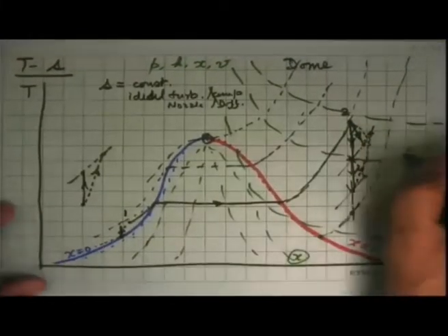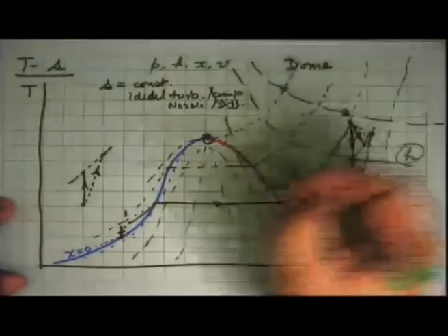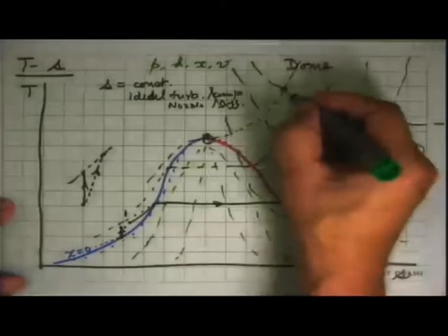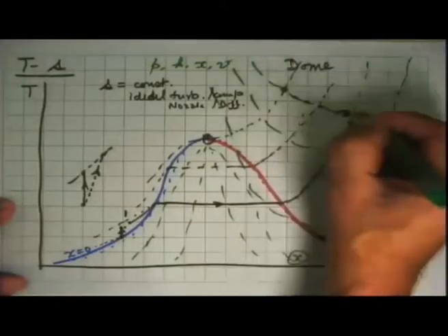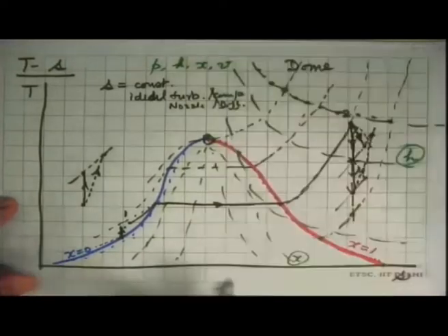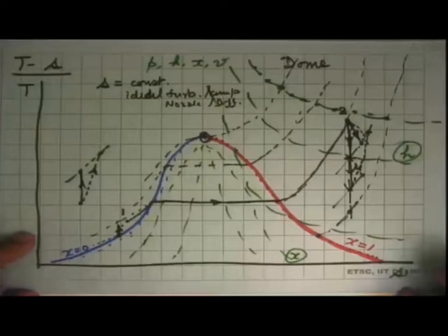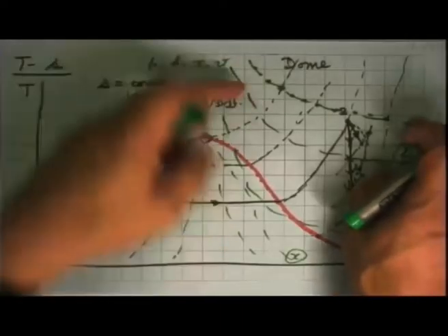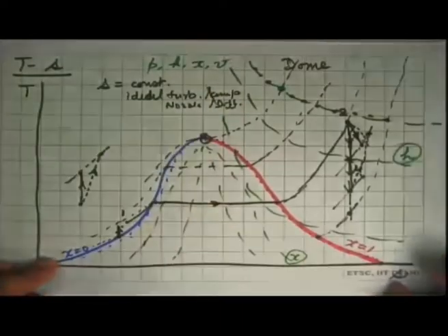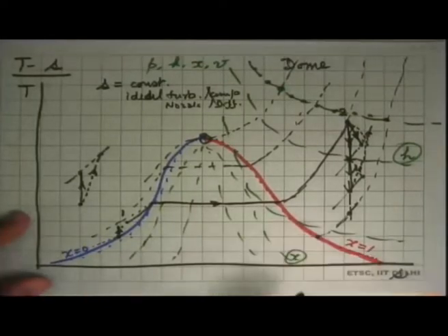So these are constant enthalpy lines. And what it tells you is that if you are going to do throttling from here, that's an isenthalpic process, then the states that one would get will be all along that side and not along this side. Throttling is an irreversible process. Entropy has to increase, so the states will lie to the right and not to the left. You cannot throttle a substance to a higher pressure. It is always to be throttled to a lower pressure.